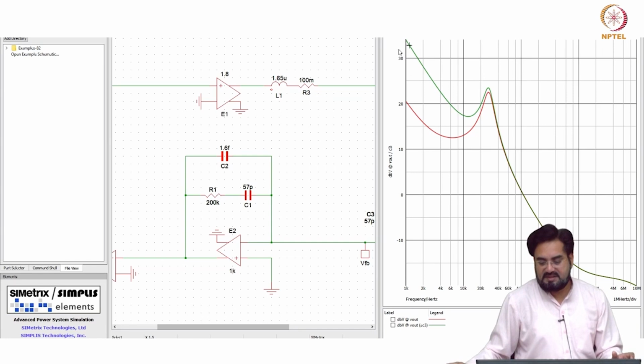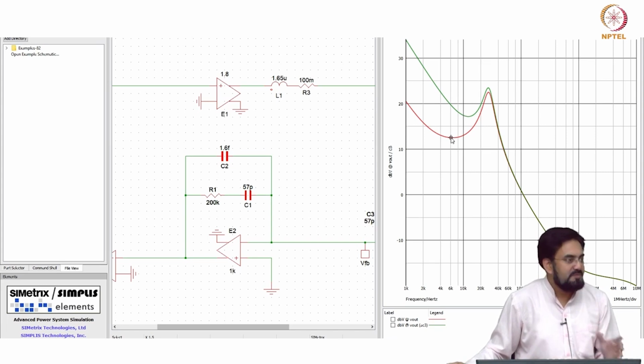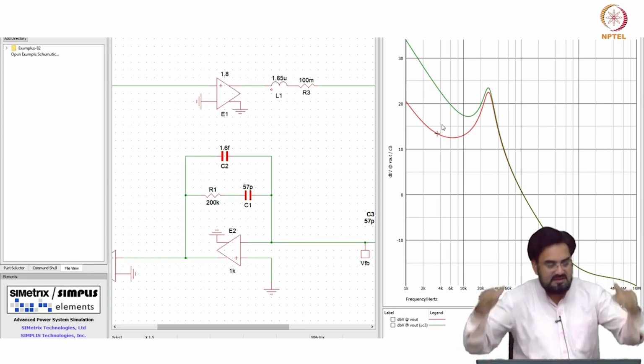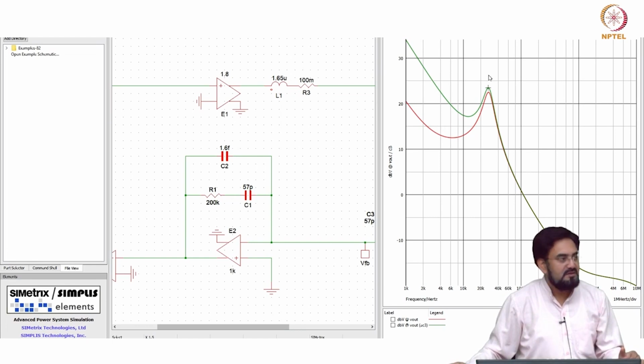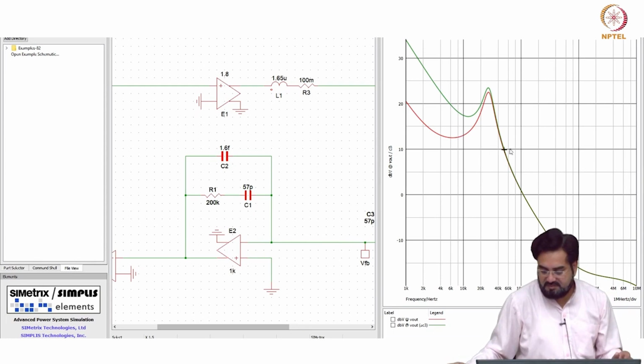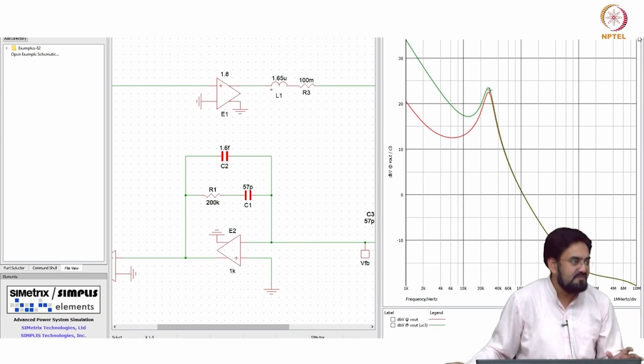So, you can see here your gain is shifted up, correct, because omega Z1 is placed at higher frequency. Which means you are placing omega I0 when gain was dropped more, but here you are placing it early when gain was higher. So you needed to reduce the integral gain, and that is what is happening, the whole curve is shifted down before you place the omega Z, or the first 0. But here if you see 0 dB, it remains the same.